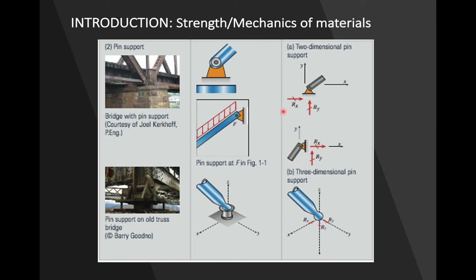Okay, so you can see this is basically supported on a vertical wall. This is the pin support in 3 dimensions. So it will transfer the incoming load onto the member in three constraints. Three constraint reactions: translation reactions Rx, Ry, and Rz. It won't allow it to translate in the x axis, y axis, and z axis, but it can rotate.